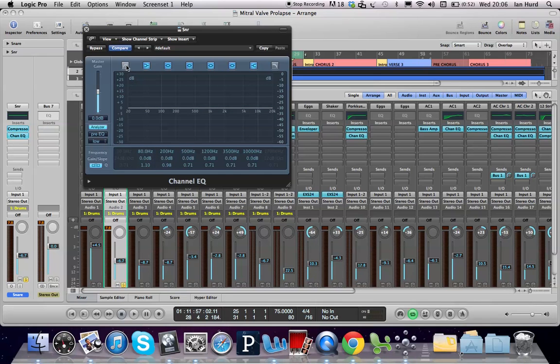We're going to select this cutoff here for the low end, which at the moment is set to 30 Hertz. That means that it's rolling off as of 30 Hertz at a rate of 24 decibels per octave. Don't worry too much about what it means, but it just means the gradient that's coming off here at the moment. So we're going to drag the frequency parameter of the first band up to 70, so that it starts cutting off at 70 rather than 30.